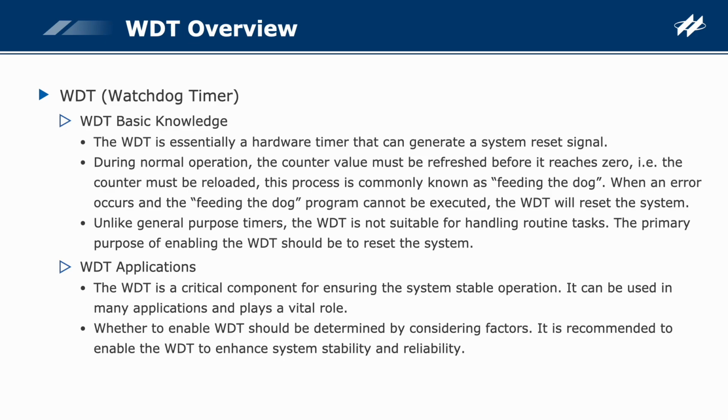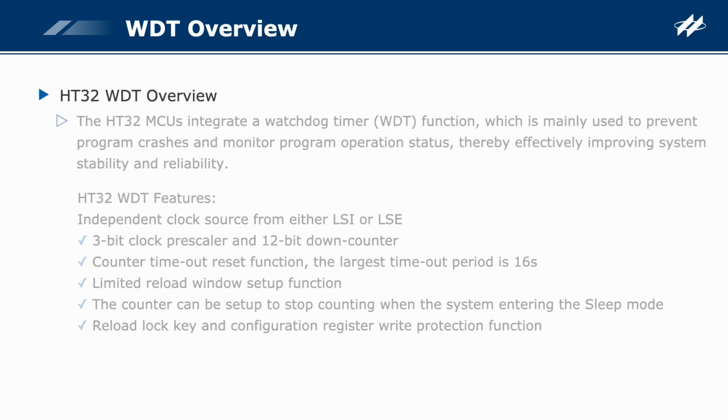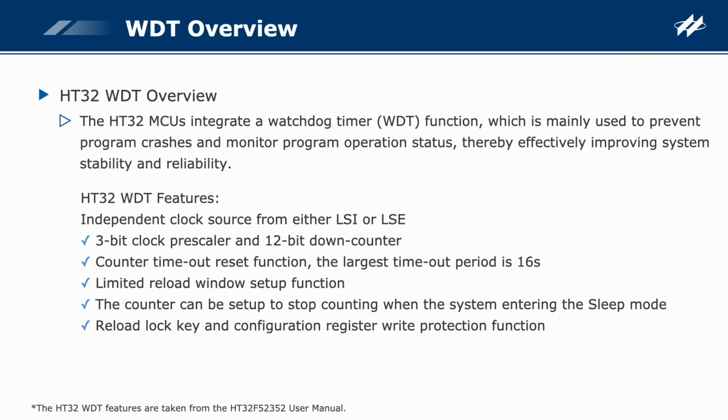Whether to enable WDT should be determined by considering factors such as the application's specific requirements, the operating environment, and the importance. It is recommended to enable the WDT to enhance system stability and reliability. The HT32 MCUs integrate a watchdog timer function, which is mainly used to prevent program crashes and monitor program operation status, thereby effectively improving system stability and reliability.